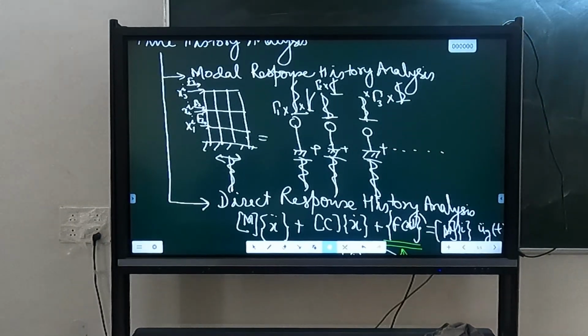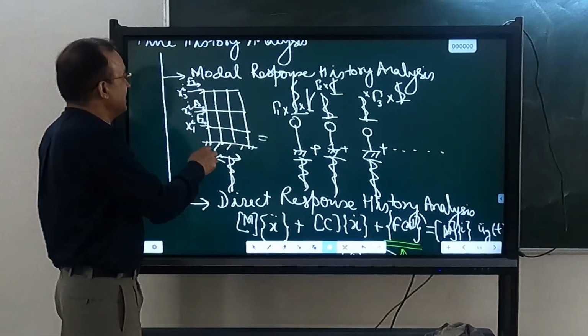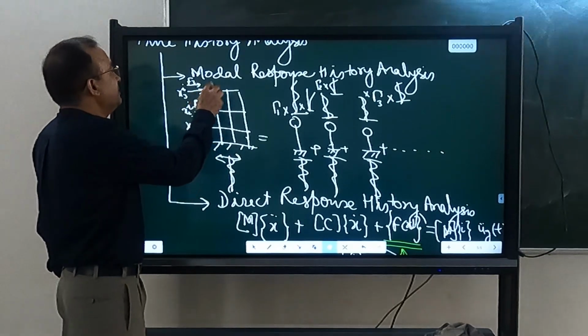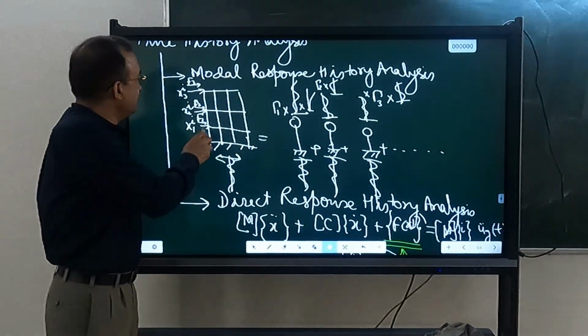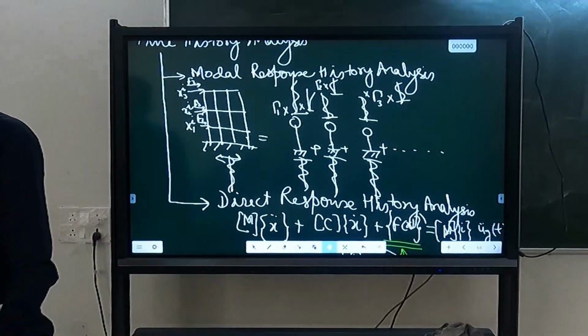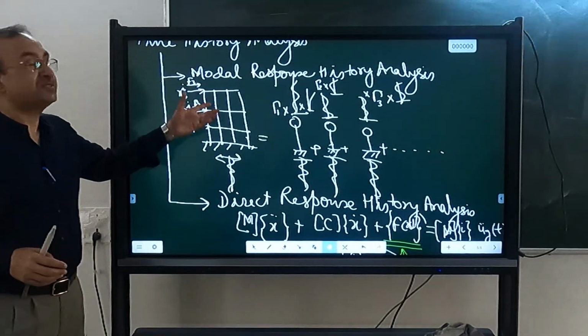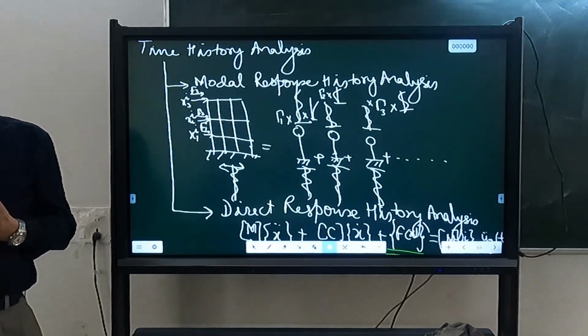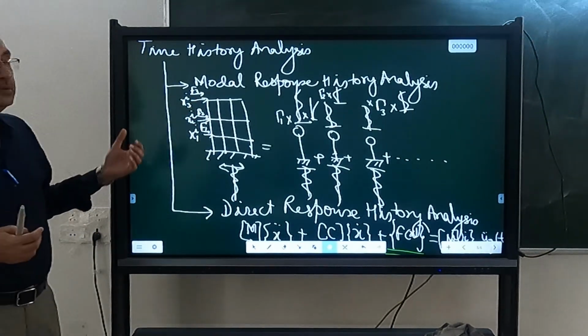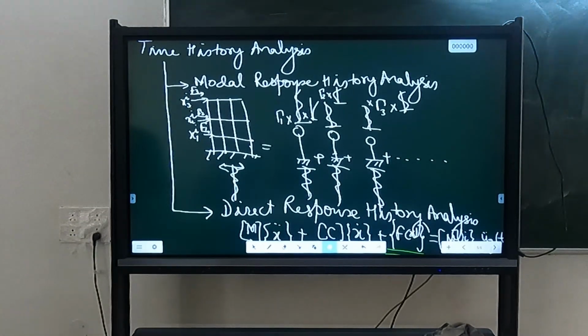The aim is, because what is happening during an earthquake, the mass remains constant. You agree? Yes. What about the stiffness? Stiffness will change. It will depend on the structure itself. That will come from the test. So stiffness will come from our capacity curve.